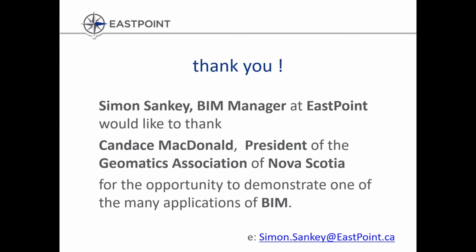But there is BIM 360, the Autodesk product, which has two products, Field and Glue, that allow you to do that. For example, if you're out on site and you've done all your formwork for pouring foundations, you could go out with your tablet and have the augmented reality foundation model on the iPad with the actual formwork in the background. You could check that formwork prior to pouring the foundation, thus eliminating a potentially costly construction error. So that typically is where I've seen it used in the past.